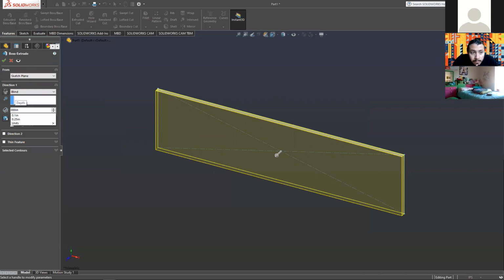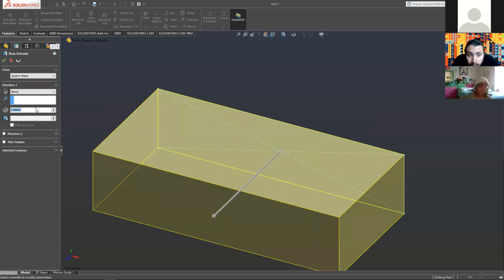You can do this like 3 inches, right? And so that'll be on this side, but it's generally good practice to have the center of your part be 0 on your origin. You get me? You want the center of your part not to be offset from the origin. So if we were to project this way, the origin would be on the edge of our part.